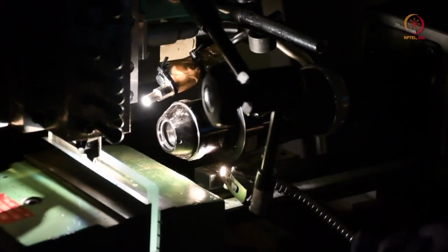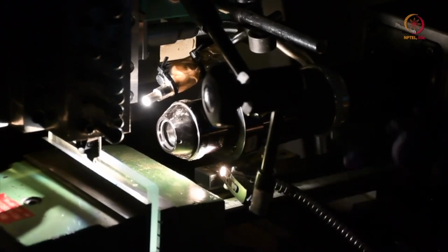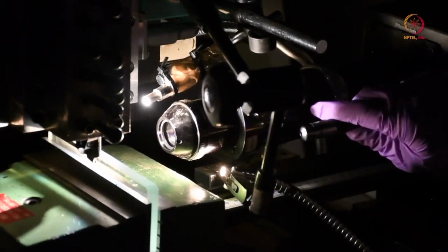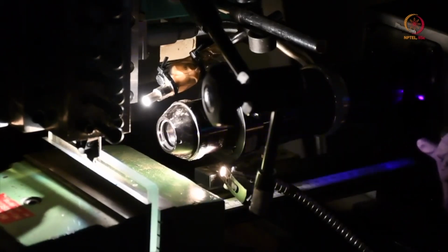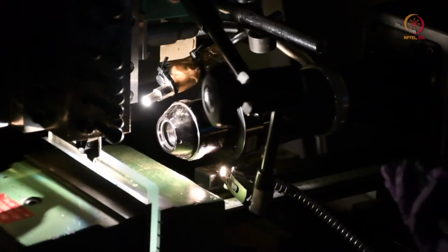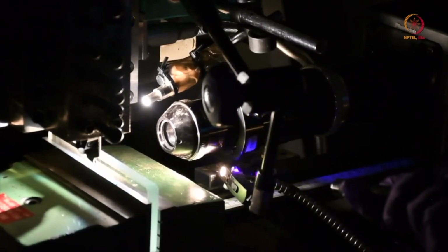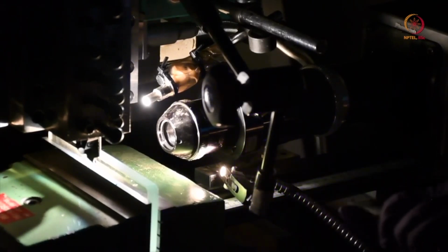So let us look at what we need to do to ensure that this region of interest is in the field of view. This lens system is mounted such that it is exactly perpendicular to the region of interest, and it is attached to a high speed camera. Since we are using a high speed camera, we need to ensure that we have a good light source. This is a fiber optic light source.